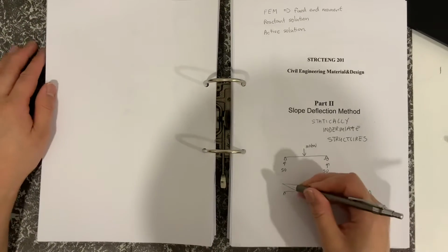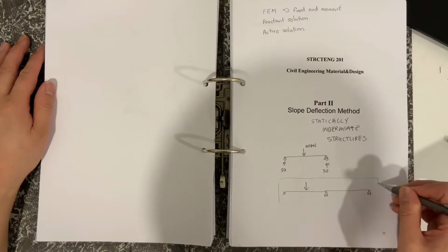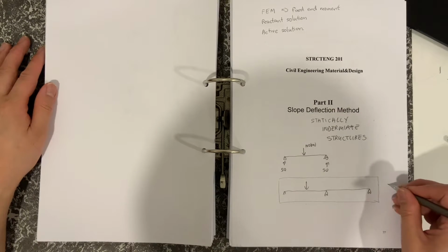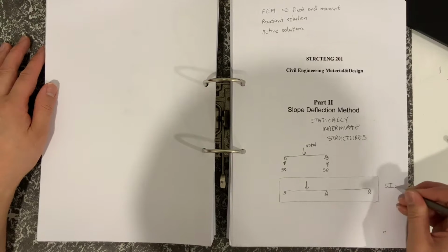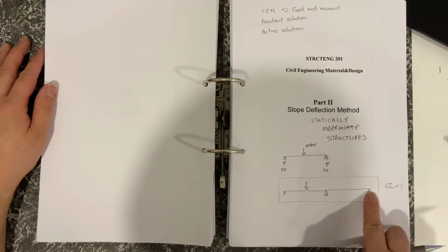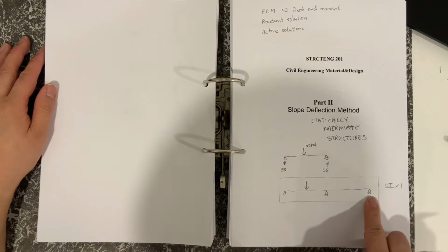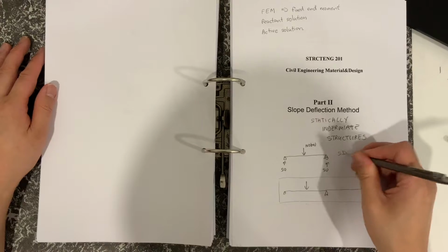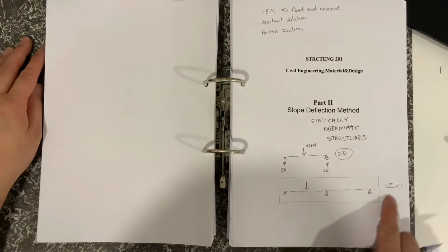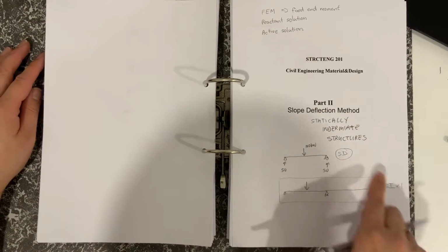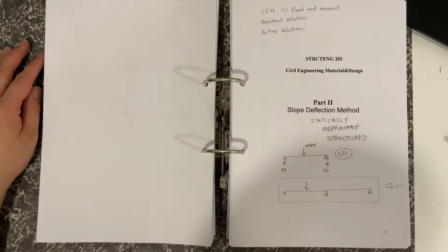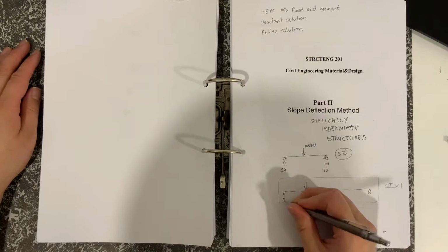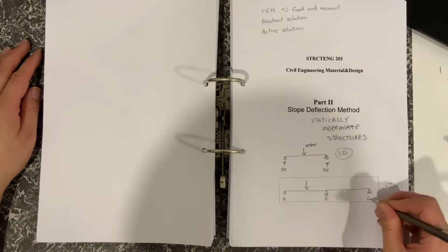So as a case here, this is an example of a statically indeterminate structure. This one is statically indeterminate by 1, because you're adding one extra unknown, which would be the vertical reaction here, compared to this one here, which is statically determinate. So the 1 signifies that you're adding on one extra unknown, which therefore needs to be calculated. So just as an example, I call that A, I call that B, and I call that C.